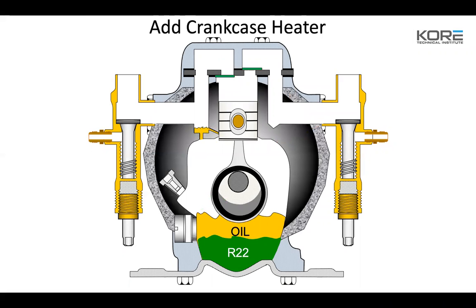If you're dealing with an indoor rack room that's temperature controlled and nice and warm, it's not necessary. You'll see a lot of racks without crankcase heaters working or even in there, because that rack room is probably always maintaining 70 to 80 degrees, and that's why they don't think it's necessary. I think it's always good to have crankcase heaters in play, because it doesn't matter what the ambient is, you're still going to have migration happening with the off cycle. The other thing about racks is they're not supposed to run static, so they're always moving refrigerant through the system, which creates a situation where the suction group isn't allowed to have migration take place.